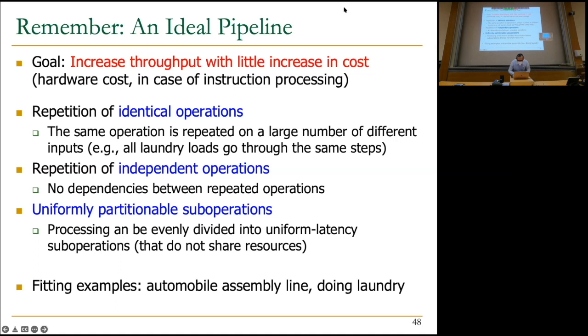Okay, let's get started. There's one question over here which says, is it safe to say a pipeline is not balanced if one stage is taking much shorter than others? And yes, I would say yes. That kind of pipeline is not perfectly balanced, basically. If you want a perfect pipeline, you really need to have an equal amount of time in each of the stages. And there's mathematical analysis of this, actually. People mathematically analyze this a lot. It becomes much harder, of course, when your machine becomes much more complicated, 30 stages, 40 stages, etc. But yes, balance is defined that way, essentially.